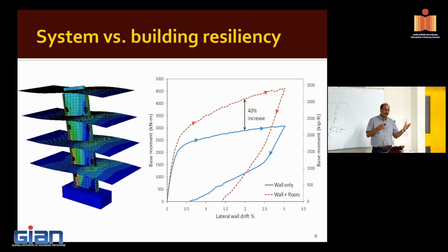When we do seismic design, again, it's not a precast problem. For any building, we don't account for the resistance coming from the floor to whatever system you're using, and the interaction. In this analysis, we've shown that it could be as significant as 30–40% more resistance. So that's something people have to pay attention to. It's not routinely done. It will show up as a problem in the future, but it's something that should be looked at.